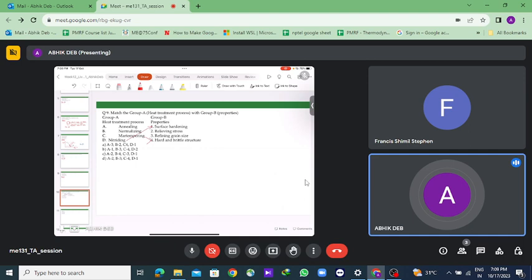See, if we are trying to reduce the brittleness by refining the grain structure, then we have to take the process of normalizing, where we have to heat to the austenitic stage and then cool in such a way that pearlite or bainite structure is formed. But for martensite, if we have to reduce the brittleness, then we will have to keep it at an elevated temperature for a longer duration of time, such that the carbon in the lattice structure of martensite diffuses out. That will result in the reduction of brittleness. That is how we will achieve the reduction in brittleness without any significant loss in hardness.